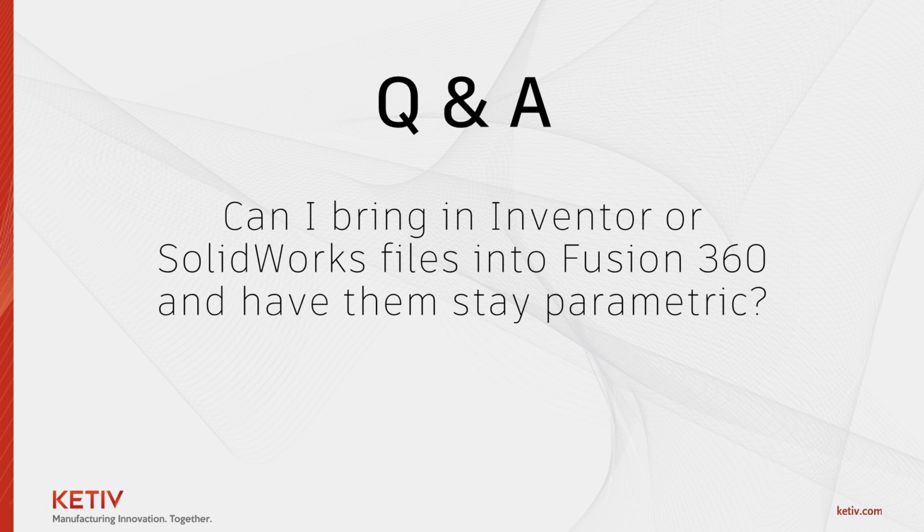Loren, do you have any insight on what else is AnyCAD capable in Fusion 360? I know they've kind of ported over some of the technology. Yeah, I see the question there. So the question was, if the company has Fusion team, can I bring in Inventor or SolidWorks files into Fusion 360 and have them stay parametric? So the answer is yes. Fusion 360's initial tech preview of AnyCAD is very specifically for Inventor and SolidWorks part files. So they're looking at parts initially, not assemblies.